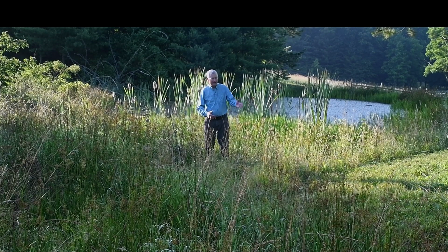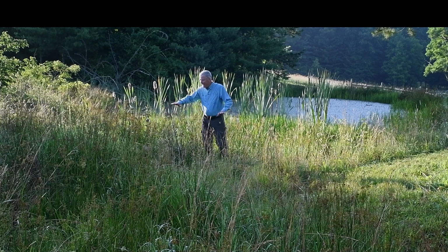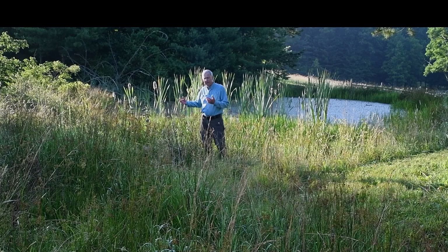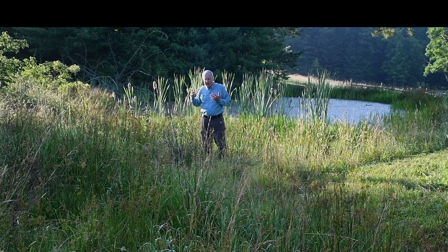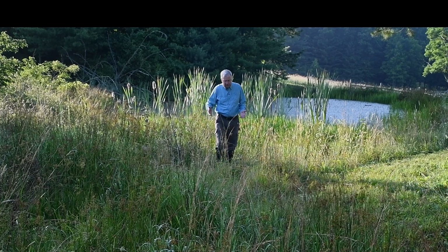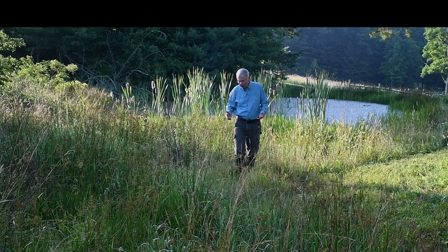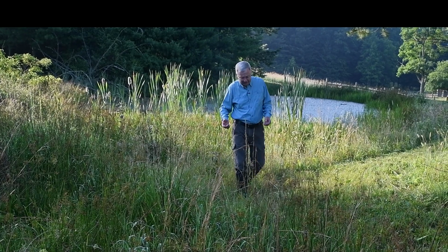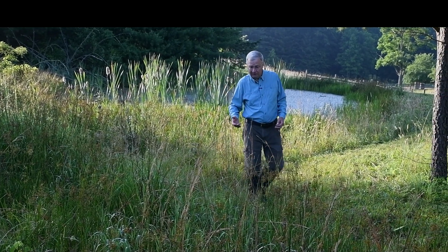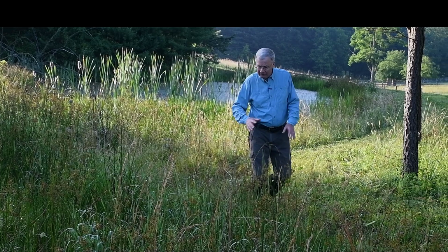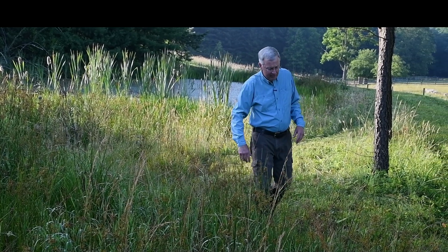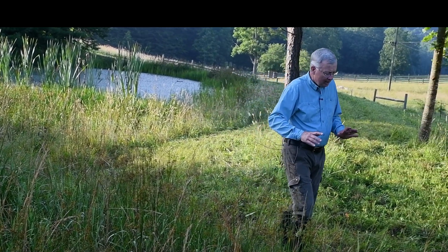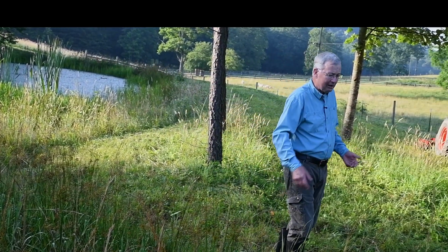It's located at one end of the dam, and it's wide, and it looks like it has a gradual slope, and it's full of these aquatic plants. It's a wet meadow. It's really important to inspect the spillway, and to do this, you should walk along the spillway and look for any erosional gullies, look for any head cuts, look for any problems. Maybe something's blocked the spillway. But what I see here is this wide wet meadow, at least 14 foot wide. The water's in a sheet-like pattern,